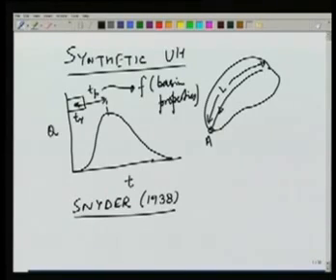The other parameter which he chose was based on the centroid of the area. So if this point C is the centroid of the catchment area, then the point directly opposite the centroid on the stream, let's call this point C prime. The distance of C prime from A, again along the stream, was termed as length to the centroid, and we would write it as LC.